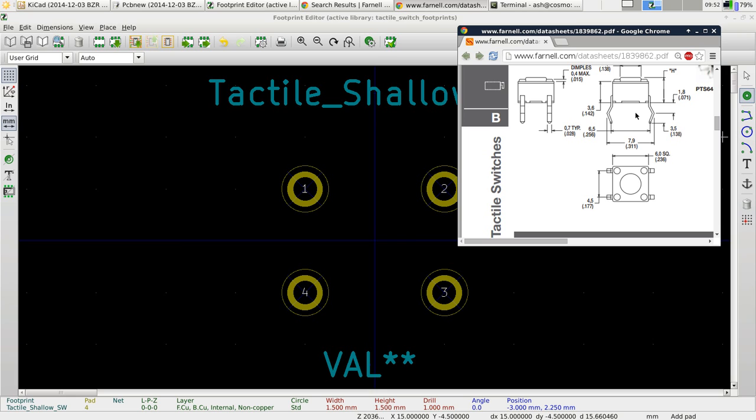I mean, if you were really concerned about this, you could try and change it. For example, they are actually 6.5mm apart, the center line, according to that. So you could do it at 6.5. Maybe we should do it at 6.5 then, just to be sure, because then we know it's directly aligned there. Assuming that they don't go out any further.